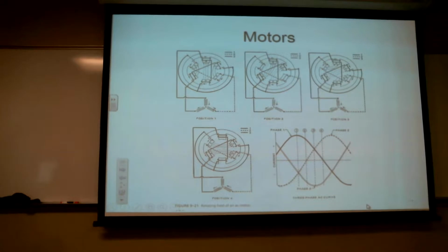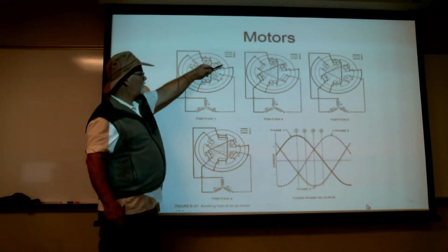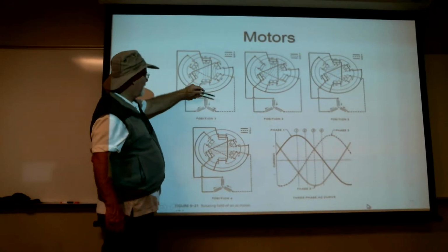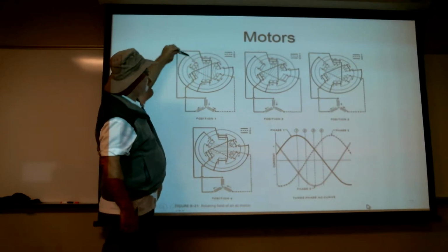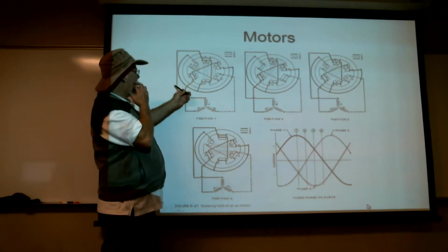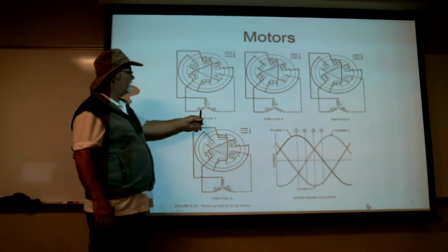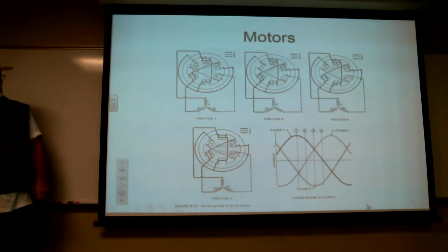Is each one of those a different phase, like when it comes around? So I've got a winding, phase 1. There, phase 1. Okay, back to here. And a winding here, phase 2. Oh, okay. Neutral. And then the winding here to there, back to the middle. Oh, okay, they're all coming to the common point in the middle. So in this case, it's Y wound.